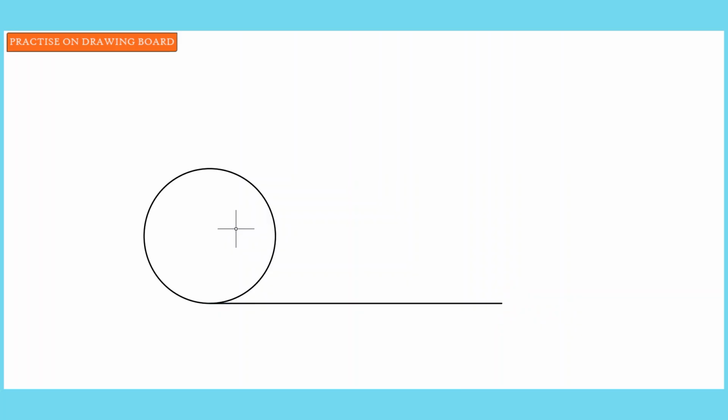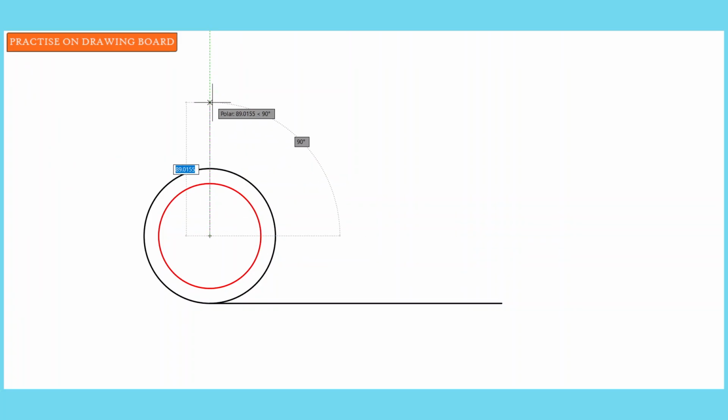So we draw that line which is tangential to the circle, and now we are ready to locate the point P, which is 35 from the center of the rolling circle and at an angle of 0 degrees to the vertical. So I just draw in a center line. Okay, so that's where point P is located.